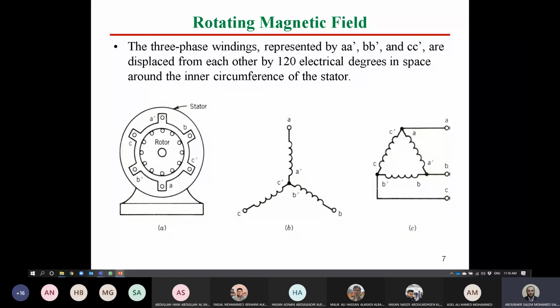For the theory of operation, we discussed recently in the synchronous machine the rotating magnetic field and its analytical relation, which was 3/2 multiplied by N I maximum cosine (omega t plus theta). This was the rotating magnetic field, and we said that because it's a sinusoidal wave, it's rotating. Now we can describe the rotating magnetic field graphically, not analytically.